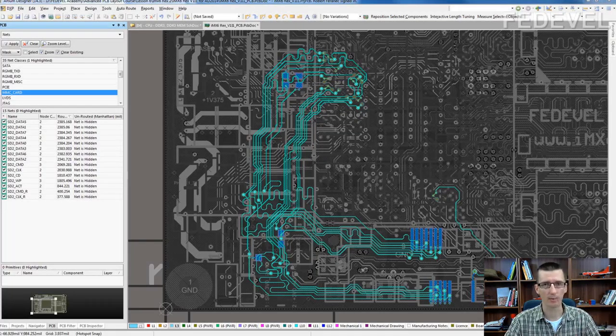Again, what I said before, once you are doing the length matching, you will do nothing wrong if the signals are length matched within 10 mils. But in these slow interfaces, it is not so crucial. And if there is no space on your board, for example, then do not hardly try to route them within 10 mils. You can be a little bit more relaxed.